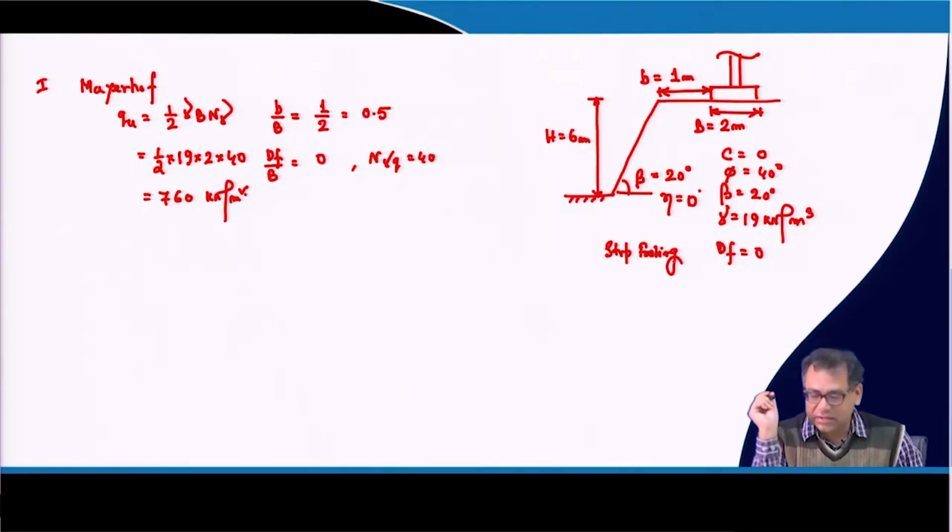But as I mentioned, if your case is a rectangular footing or square footing, and you have other conditions or loading conditions like inclined load, or soil compressibility and all the other factors, then you have to use those factors here with some caution, because originally it is developed for the strip footing. Okay.